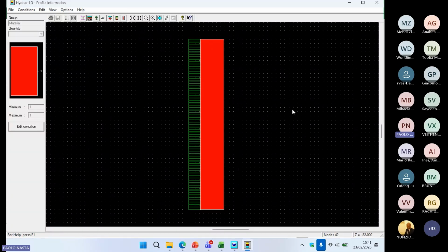And so this is the setup of the soil profile. I hope you see the window, so you see the discretization. By default, there are 100 nodes. We said that so far we have only one layer, so you see that the color is uniform because we have a uniform soil profile. Here at the bottom right of your window, you have the zeta. When you move your pointer back and forth, you see that the zeta changes.